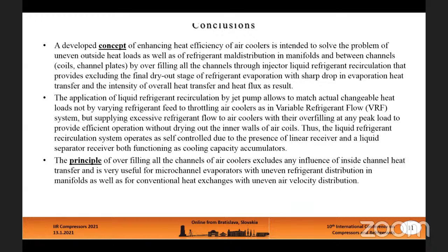The application of liquid refrigerant recirculation by jet pumps allows to match actual changeable heat loads, not by varying refrigerant feed to throttling air coolers as in variable refrigerant flow systems, but supplying excessive refrigerant flow to air coolers with overfilling at any peak load to provide efficient operation without drying out the inner walls of air coolers. Thus, the liquid refrigerant circulation system operates as self-controlled due to presence of the linear receiver and the liquid separator receiver, both fluctuating as cooling capacity